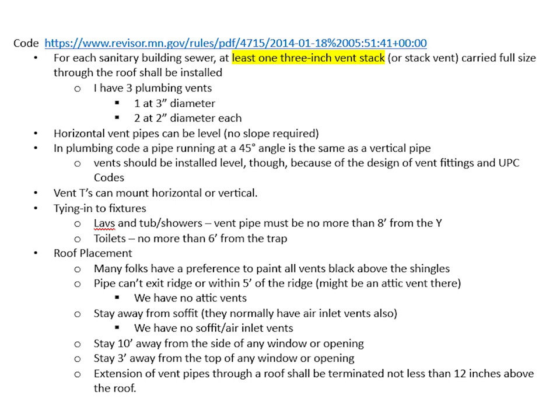Here's some additional guidance on vents. Code is listed below. For each sanitary building sewer, at least one 3-inch vent stack or stack vent carried full size through the roof shall be installed. I have 3 plumbing vents, one at 3-inch diameter, 2 at 2-inch diameter each.